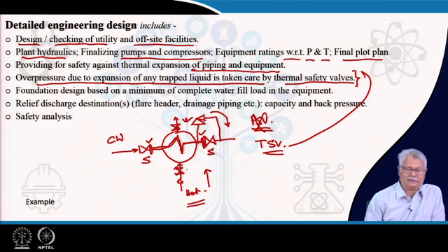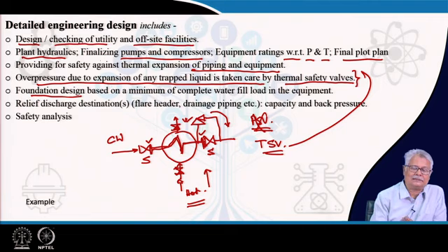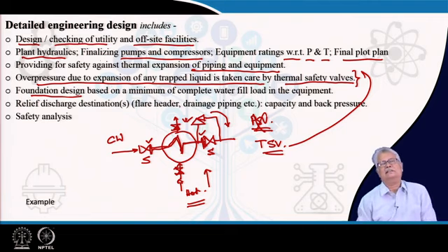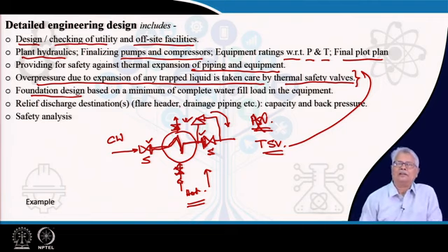You will also notice the next item. The foundation design is finalized in the detailed engineering design stage, and the minimum load that has to be carried by the foundation is a complete water fill load in the equipment.